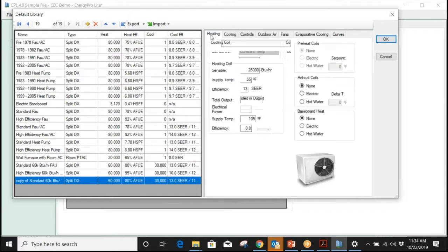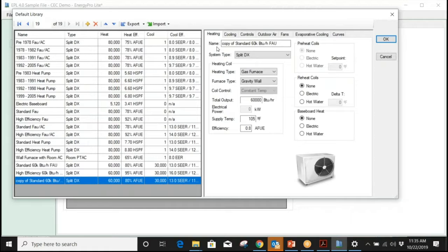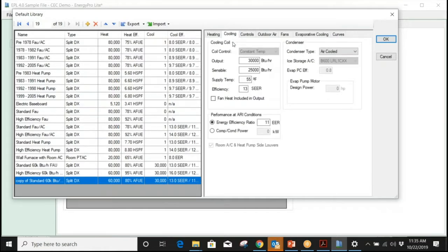Can you go back to the heating for a second? We'll do a heating hot water example later. All right, so going to cooling for this specific system. You're outside, you're looking at the condenser. You're going to make a model, and so this information that you see here in the cooling coil section might be listed there. You might have to get back to the office and look up the spec sheet for this model. Pretty straightforward what you're entering here.